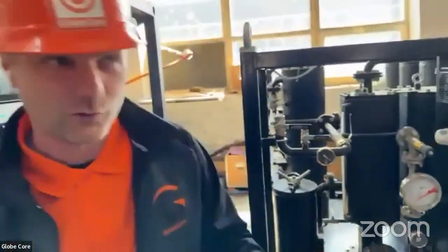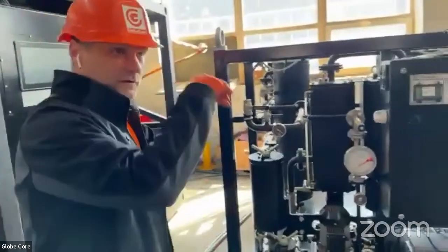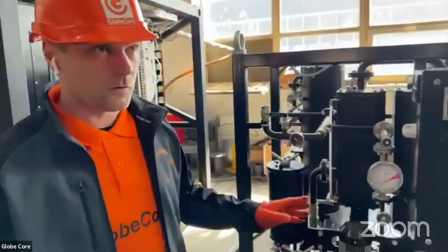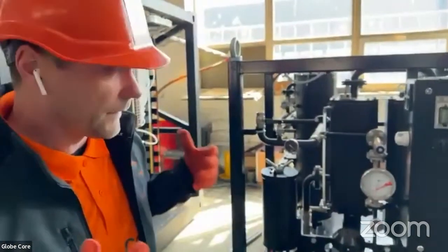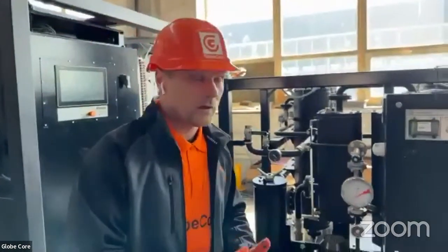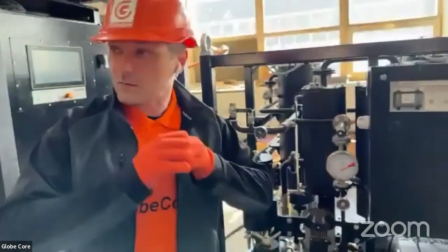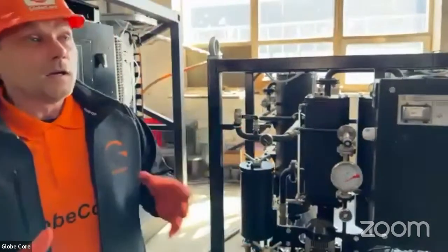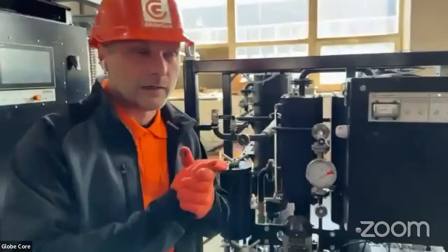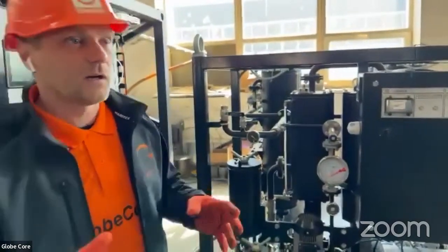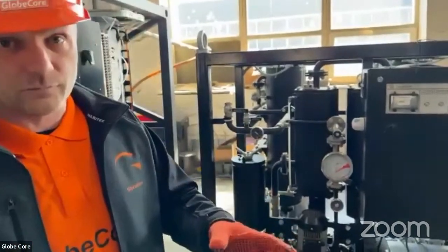In fact, this is all about the implementation of the regeneration process. We just take oil, push it through the sorbent, and refine it at the fine filter, and this is all. The biggest advantage of this technology is the ability to reactivate the sorbent. By reactivation of the sorbent, we understand the total reclamation of the sorbent's sorption ability. As it was said, it is done by burning out the sorbent, burning out all the impurities collected by the sorbent during the regeneration process.